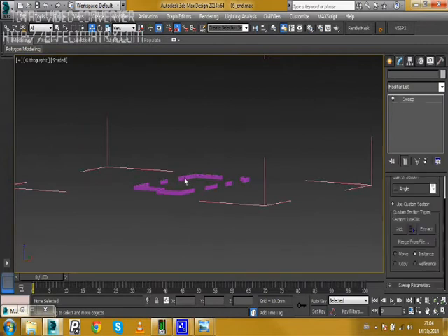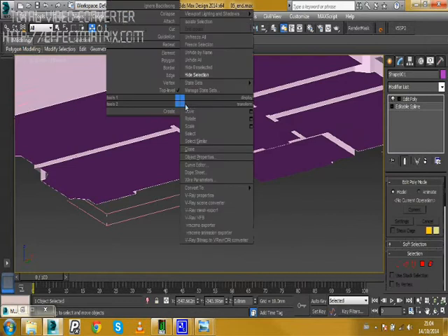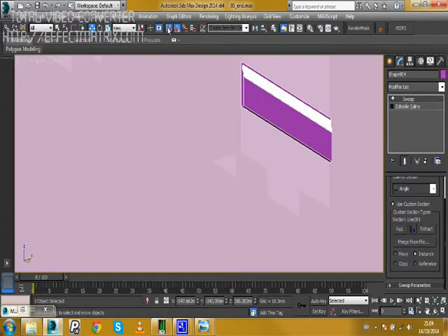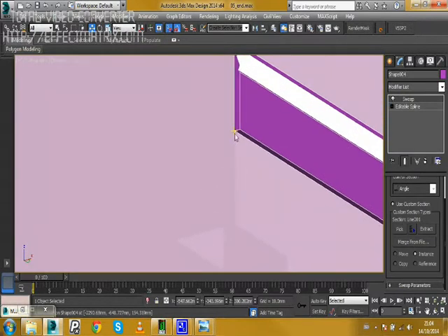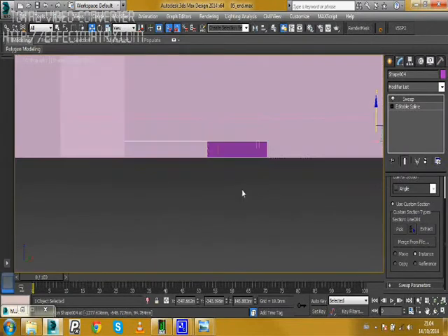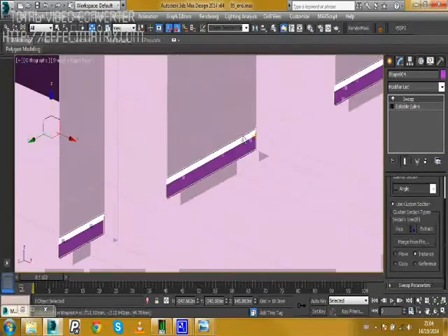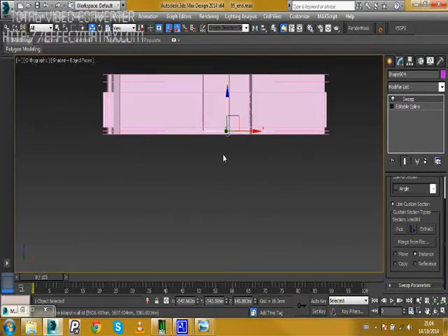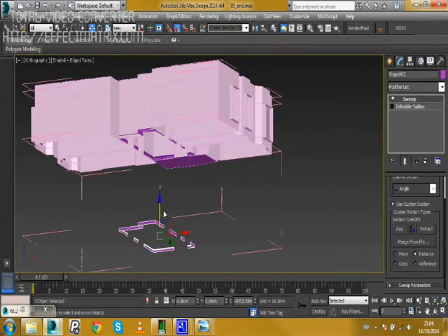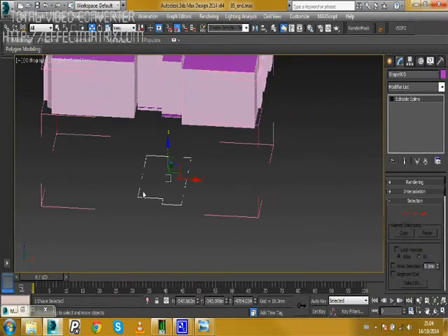So we just select our skirting and we'll drag it up. I'm just going to hide the floor for just now. Turn on your 3D snap. We'll just snap this down there, like so. So now we have our skirting in, we'll look at creating the cornice. Before we do this, I'm just going to take a copy of the skirting, shift and drag it, and just delete the sweep off it. We'll use this line for the cornice.